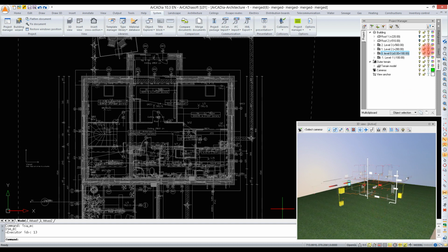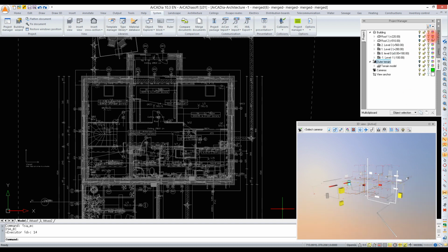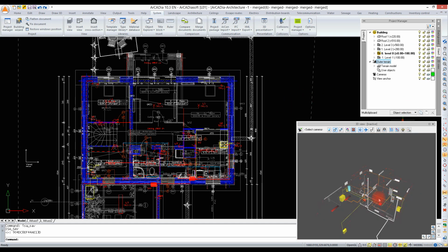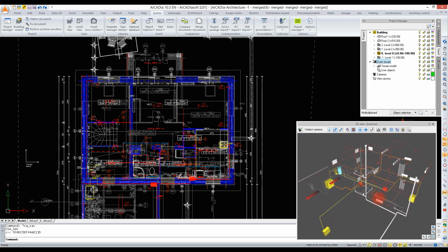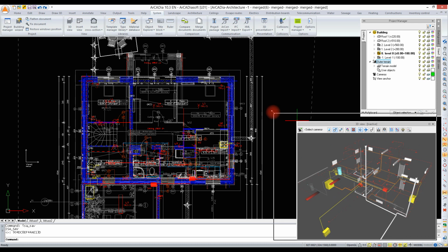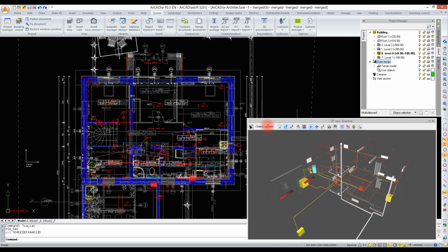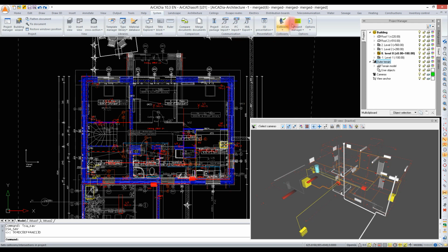It is good to also check collisions between architecture and individual installations, but for now we will only do the installations. I do not recommend checking for collisions of everything at once, as there could be too many things marked and it would be difficult to figure everything out. It is better to select 2 to 3 installations and to check them one by one.